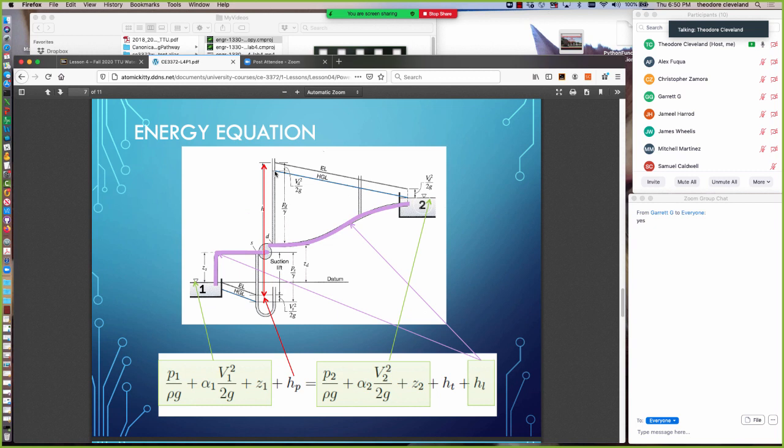And then because the water is moving, it has a little additional head, the velocity head, and that's how we get from the hydraulic grade line, which is the position where water would rise in a bunch of pipes that were attached to this pipeline, or if you could visualize a slot going all the way up to the moon, that's where the water would appear. That line is the hydraulic grade line. So it locates where the water surface would be if the water could have a surface.